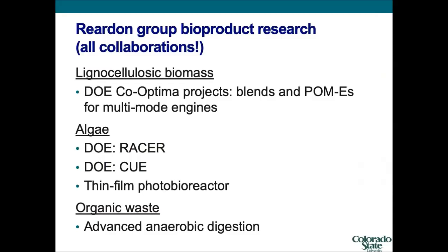Some of this is about a new class of engines. They have different names, but the general concept is that they're called multi-mode engines. They sometimes act like spark ignition engines, our cars, gasoline burners, and sometimes like diesel engines, which are compression ignition. The combination of the two can result in much better fuel efficiencies. But then the question is, we're really good at making gasoline for today's engines. What should the new gasoline or the new fuel look like? It can't look like gasoline.